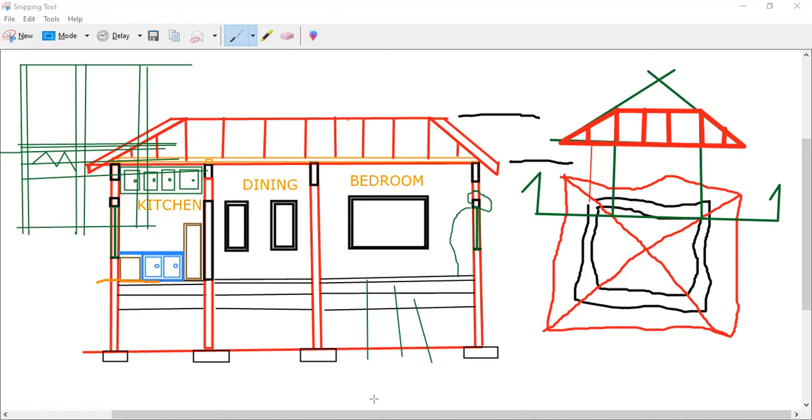From that, you would then draw your footing. What I normally ask my students to do while drawing traditionally is that once you get this, you trim this section. You trim out here, trim here, trim off this section, to get something looking like this. I typically draw my footing someplace in the drawing, then copy and drop it onto these. Once I trim out the section, I would be left with something like this.